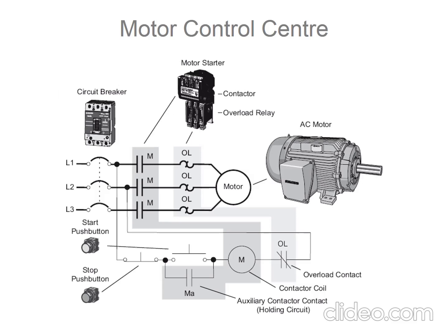This is the diagram of the motor operation. We can see here the live supply, and then we have the start push button. This one is for the circuit breaker, and then we have the push button to start the operation. This is the motor starter, and this is the overload relay for protection, and then this is the operation of the motor. This is the single-line diagram of the operation.